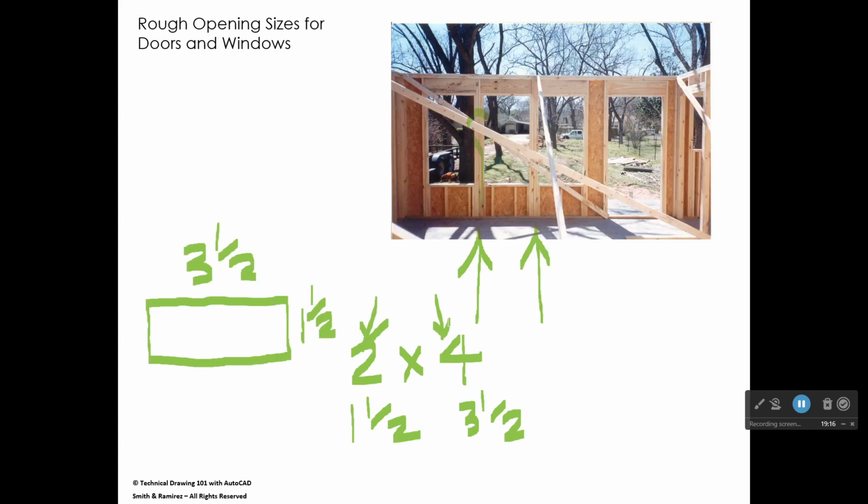And so what happens is when they cut the wood for a 2x4, it's wet. The wood is wet because it was a tree not that long ago. So what they do is they cut it 2 inches by 4 inches, and as the wood dries or cures, it shrinks because it loses moisture. So by the time we're framing something, usually our 2x4s measure 3.5 by 1.5.